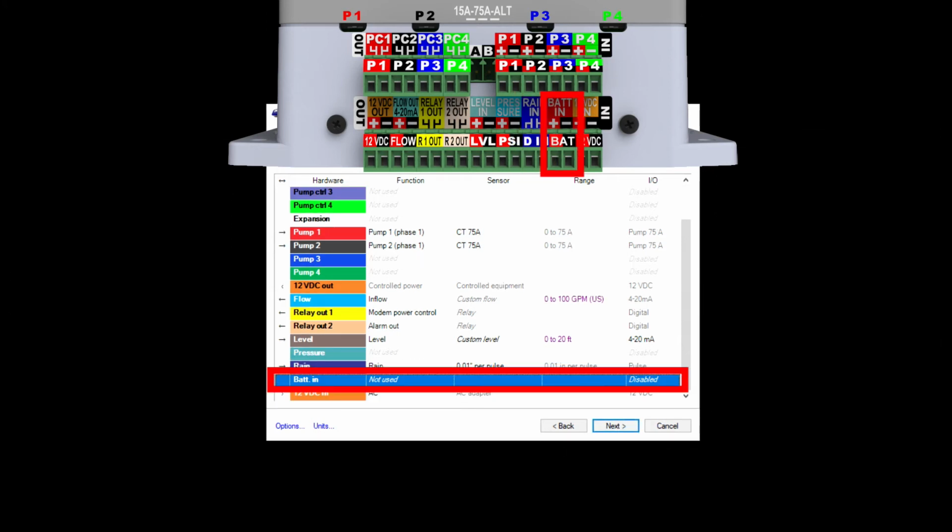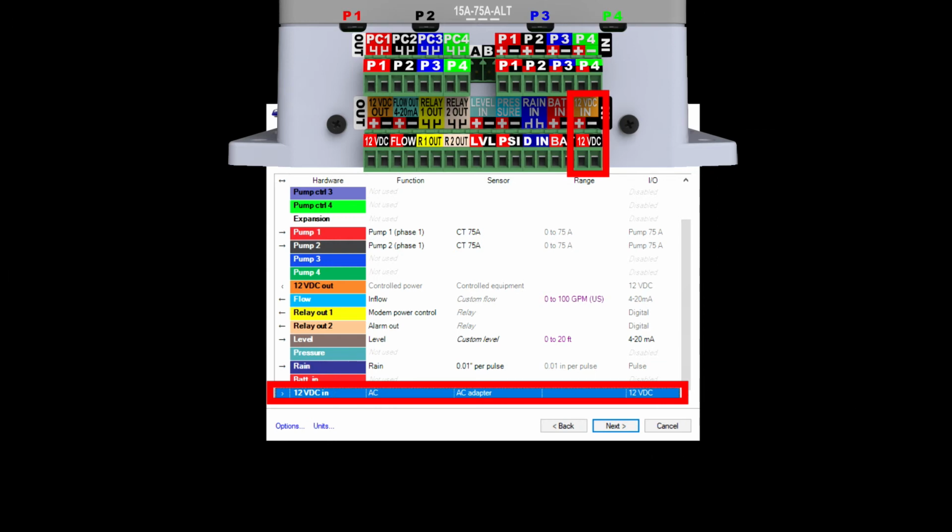The battery end connection is for the main or battery backup power, so it keeps the device running even during a power failure. This can be useful if you want to be warned that there is a power failure and that the level has just become critical. The device manages the battery charging functions. The 12 VDC in is actually a 12 to 24 volt input.